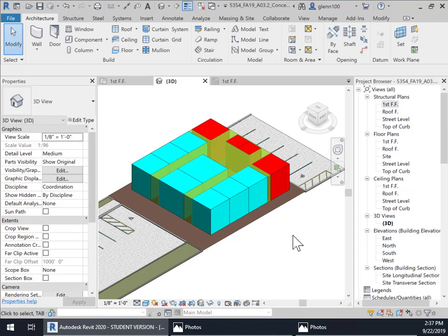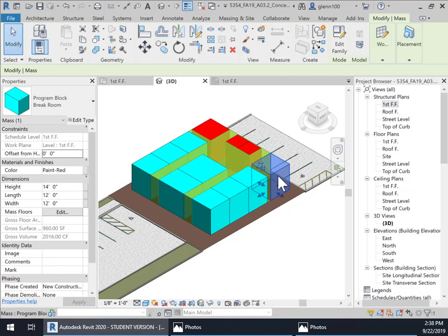I'm just going to start off doing walls. I could do the floor plate first, but I'm going to let my floor plate move in shape as I start to refine my rooms here. Since I already know some dimensions, a couple of things I'm going to do. I like to use grid lines, even though I may not use them structurally later, to create points from which to measure. Since this room is 12 by 12, yeah, 12 by 12. All of these offices are 12 by 12. And then these are 16 feet wide, right?